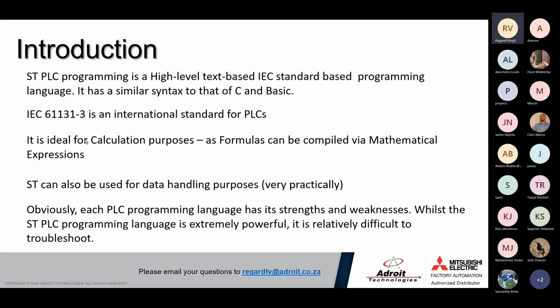The structured text is very powerful, ideal and practical for mathematical calculations and expressions. Also for string handling and data handling, it's very practical. Although the other languages can do that as well, structured text is more suitable for it. Each language has its own strengths and weaknesses.